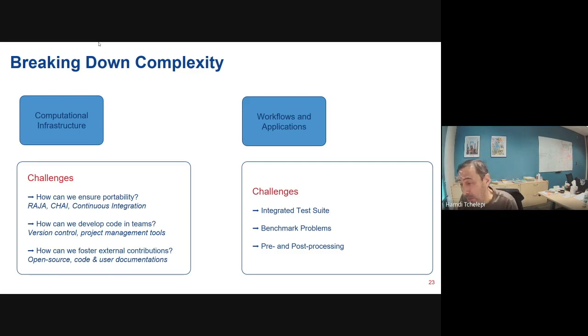You have to account for heterogeneity, which is highly discontinuous permeability fields. You have to account for the presence of fractures, even though you don't know exactly where they are, but you can't smooth them out because they're important to the physics. And then you have to do all of these computational models with high enough resolution to resolve the fluid dynamics, the nonlinear dynamics, like the fingering I showed you. And then you have to cast a prediction within a probabilistic framework so that people can design these models and can use your simulation framework to design it, but also to monitor and mitigate as things go wrong.